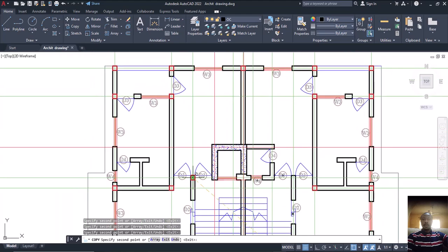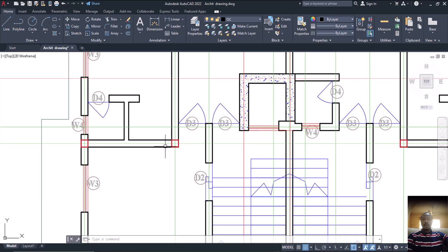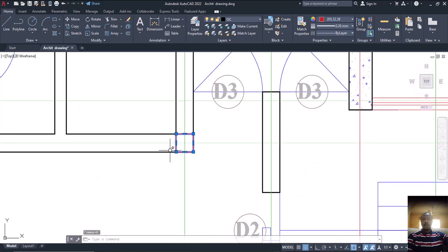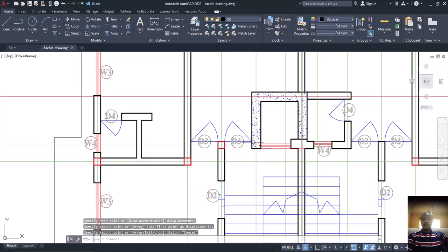So now it then means that, let's now reason it out. It then means that I will definitely need a beam that will run from here to this place, because if I put a column here, let's do it, it will be too close to each other. These are the ways in which a structural engineer will think, will reason. Is that okay? If I put another column here, I don't want to put a column here because this is already a wall. The wall is also your column. Is that okay? So that is that.